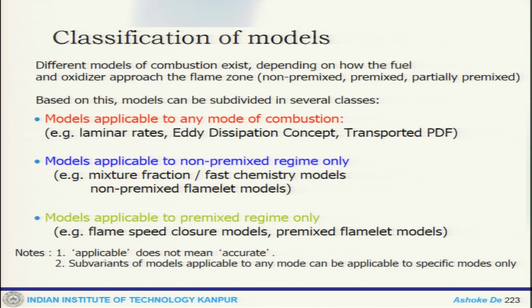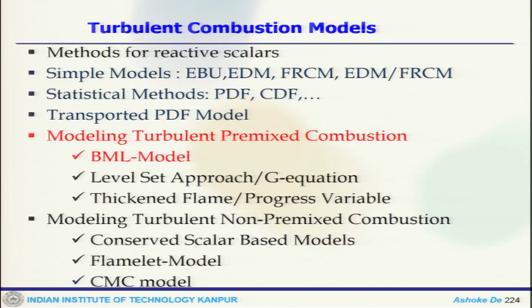Now one can classify these models. So the classifications: we have already seen the modes of application to any mode, which is laminar, and so on. Models which are applicable include mixture fraction, fast chemistry based models, or non-premixed combustion. These are applicable to any mode of combustion. These are very specific to premixed combustion, and these are specific to non-premixed combustion.